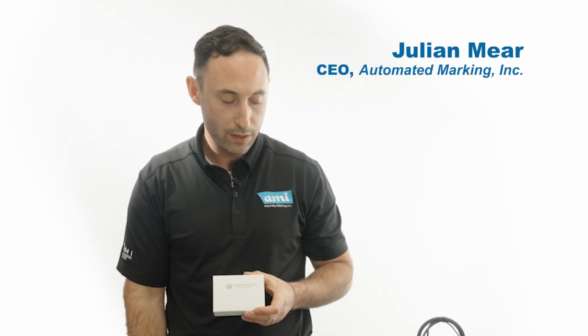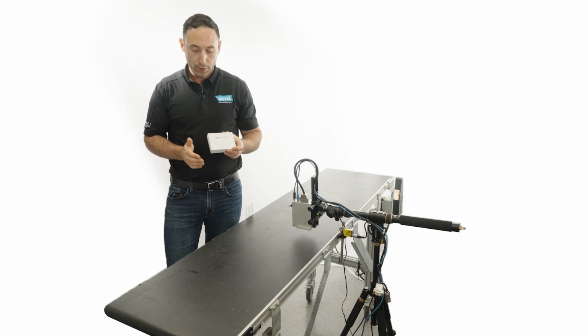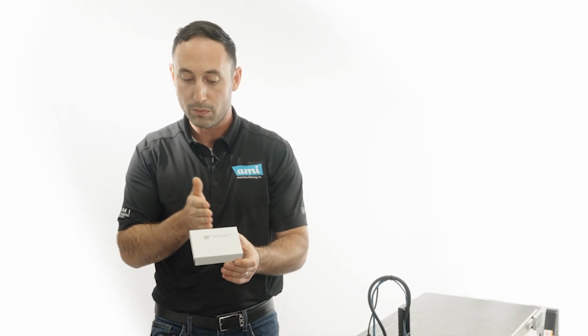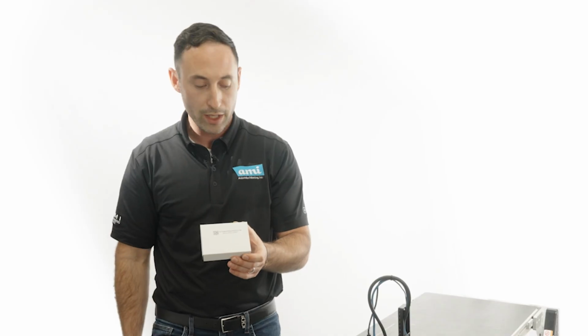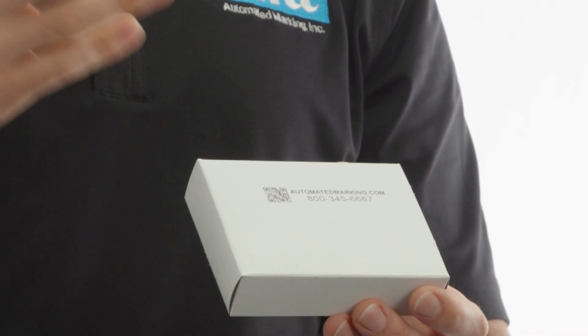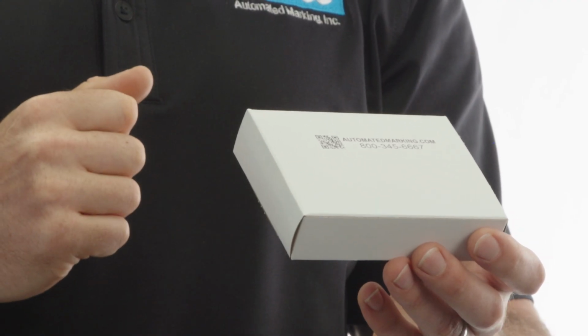So the next key parameter for high quality print here that I would like to discuss is print delay. Print delay, simply put, is when the product sensor here sees the edge of the product here and how long it waits before it actually triggers that print. So here you can see we have a rather centered print, and that's because we set the proper print delay in the software. So we're gonna go through the next steps and show you how to actually set that print delay in the software and show you what happens when we increase and decrease that delay and the effects that that has on the print.